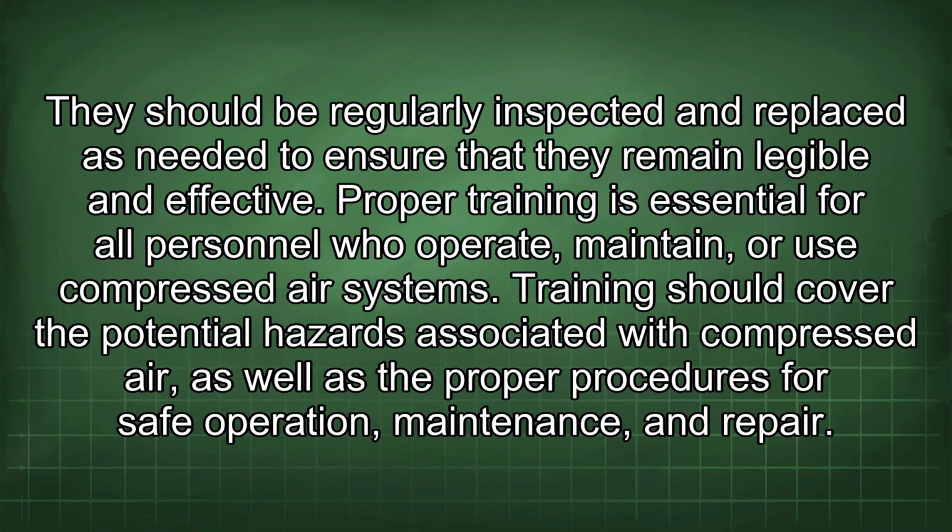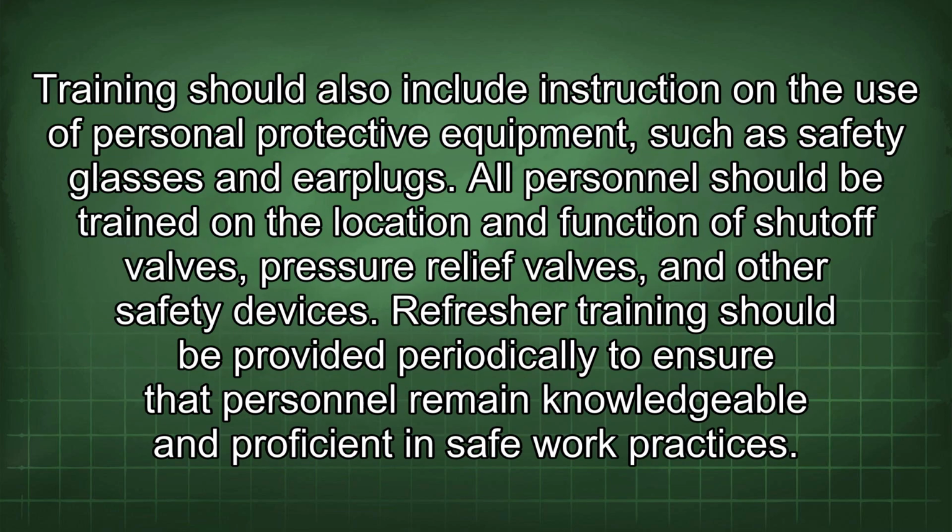Proper training is essential for all personnel who operate, maintain, or use compressed air systems. Training should cover the potential hazards associated with compressed air, as well as the proper procedures for safe operation, maintenance, and repair. Training should also include instruction on the use of personal protective equipment such as safety glasses and earplugs. All personnel should be trained on the location and function of shut-off valves, pressure relief valves, and other safety devices. Refresher training should be provided periodically to ensure that personnel remain knowledgeable and proficient in safe work practices.